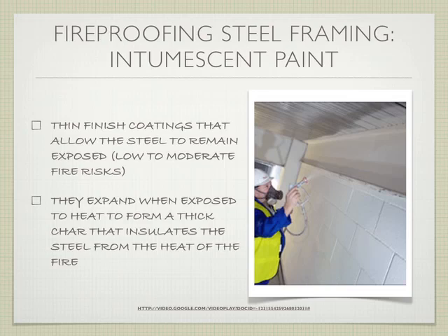I guess this is intumescent paint. The other option that we have is putting on a finished material that finds a way to make it look good, but still provide some fire-resistive properties. The thing about something like this is it needs to be in an area where there are low fire requirements.